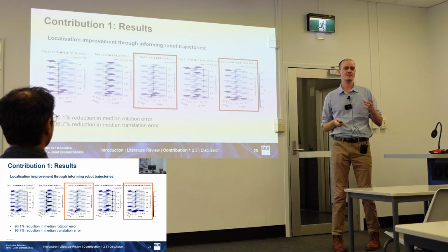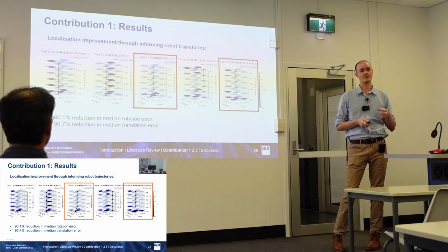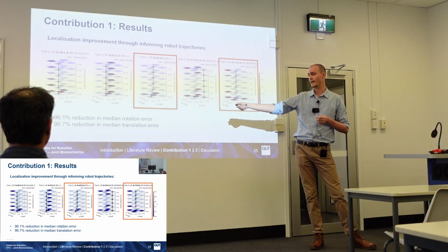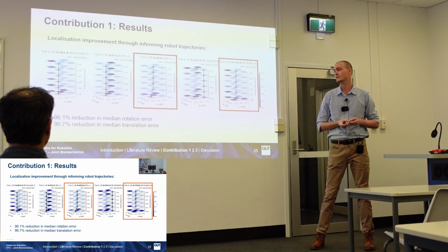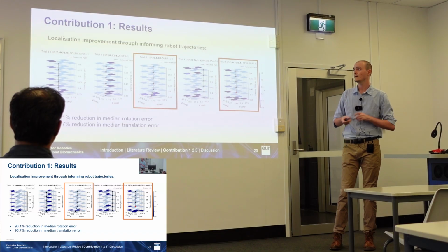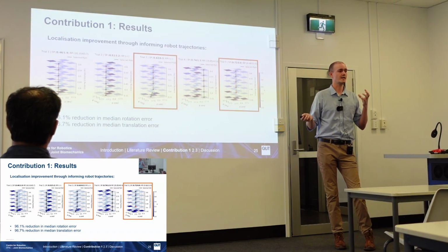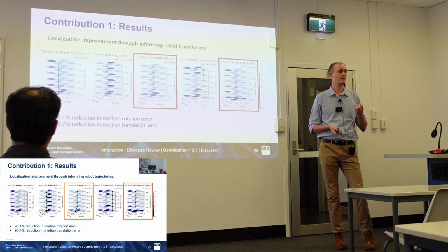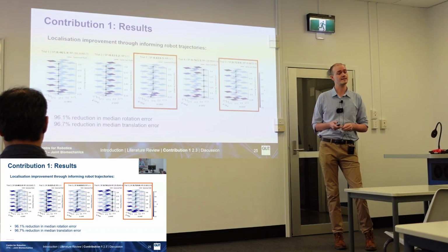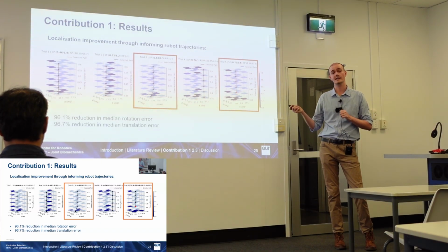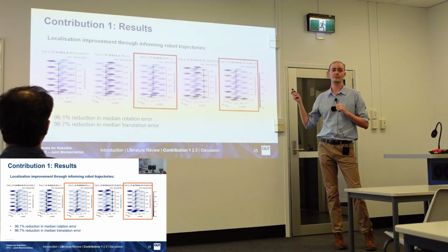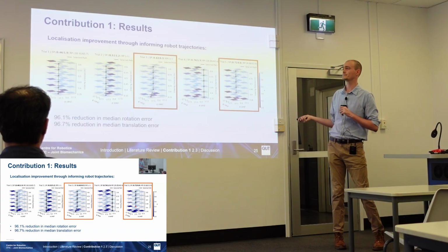Comparing localization accuracy across the trajectories selected by our approach and the trajectories rejected by our approach, we can see a really significant reduction in errors here, with a 96% reduction in both rotation and translation errors. Collectively, these results show that we can use performance heuristics from within a 6 degree of freedom pose estimation system to infer performance of the localization system. Importantly, these localization self-assessment methods can provide a lot of opportunity to improve performance by reducing errors.